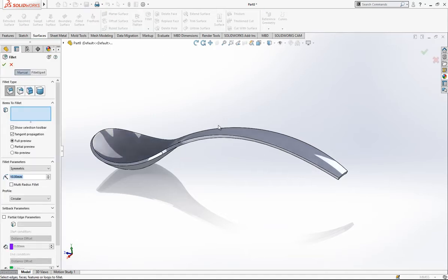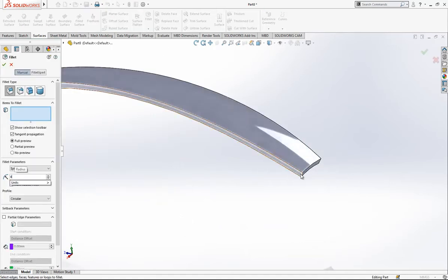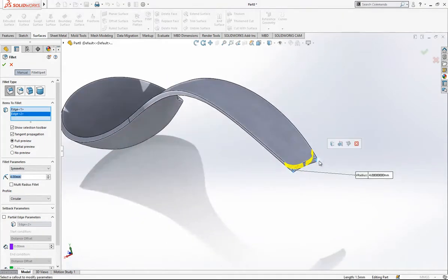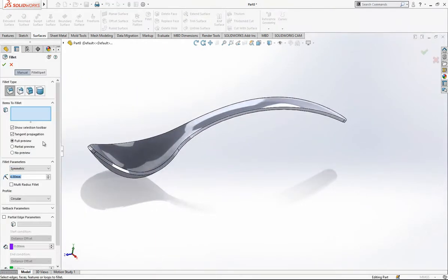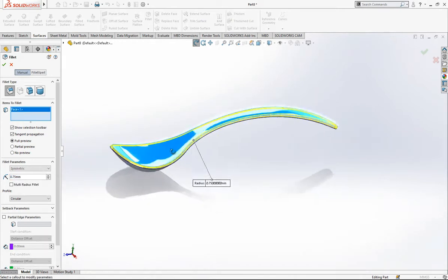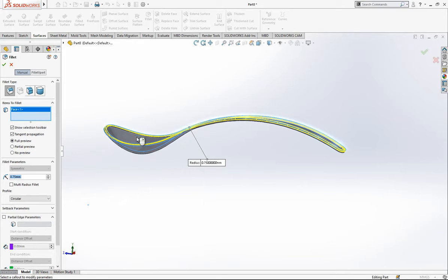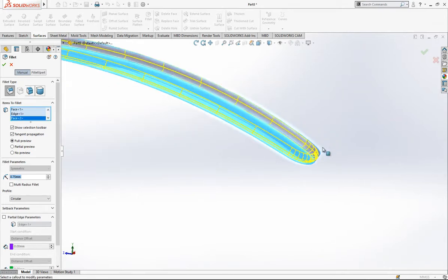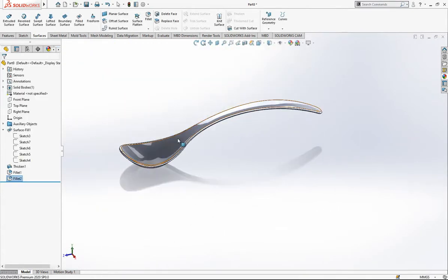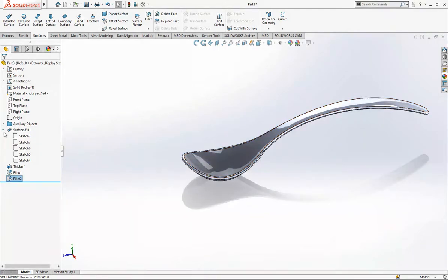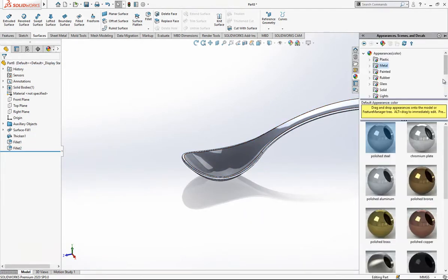And then let's place two radii here by clicking our edges. Yes, and then final radius 0.75. In fact, clicking on a surface will do the same thing for us instead of choosing the edges. The model is finalized now. I hope you can also follow these steps.